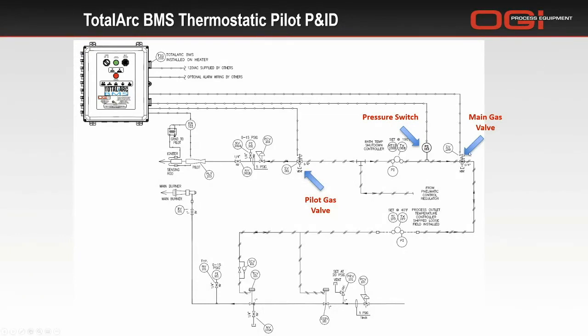At that time, that gas valve will provide gas to the process controller. In many cases, there will also be a bath temperature controller in line with this controller. After that, it will provide gas to both the temperature control valve and the safety shutdown valve.